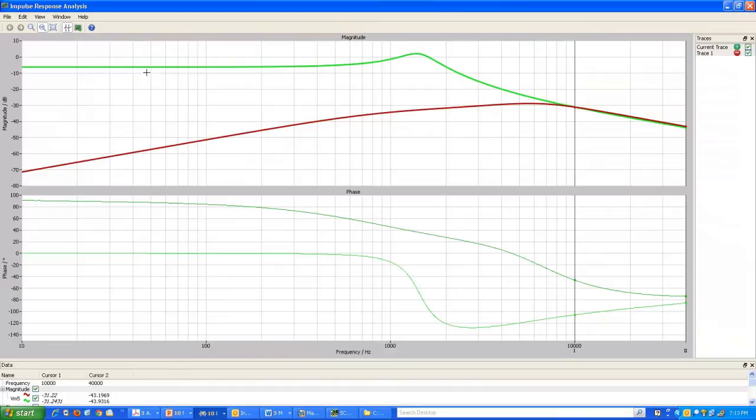So here the upper plot, the green plot, is what we got under the open loop control condition, and the red corresponds to the closed loop condition, and once again it is the transfer function from input voltage disturbance to the output. Clearly we see again about a 60 dB improvement in the audio susceptibility transfer function. So it means that if there is some perturbation, one practical example is perturbation at the line frequency or twice the line frequency, like 60 Hertz or 120 Hertz, when your input is derived from a rectified AC, line frequency AC.